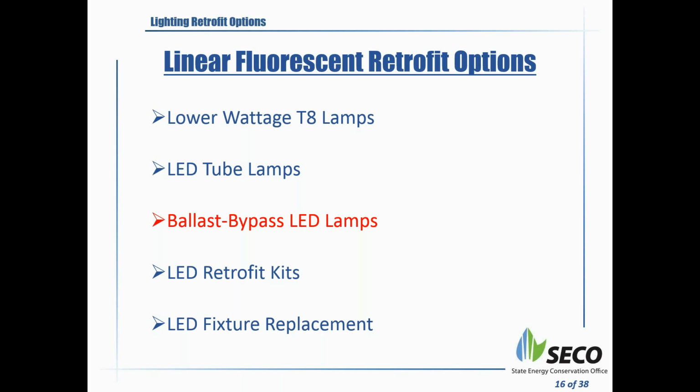The other option is you consider the whole fixture replacement. So not too many people do that, but some do that. If you've got fixtures that are 25, 30 years old, it may be time, and they're not in good shape, it might be time to do the whole fixture retrofit, and you just replace it with LED fixtures.